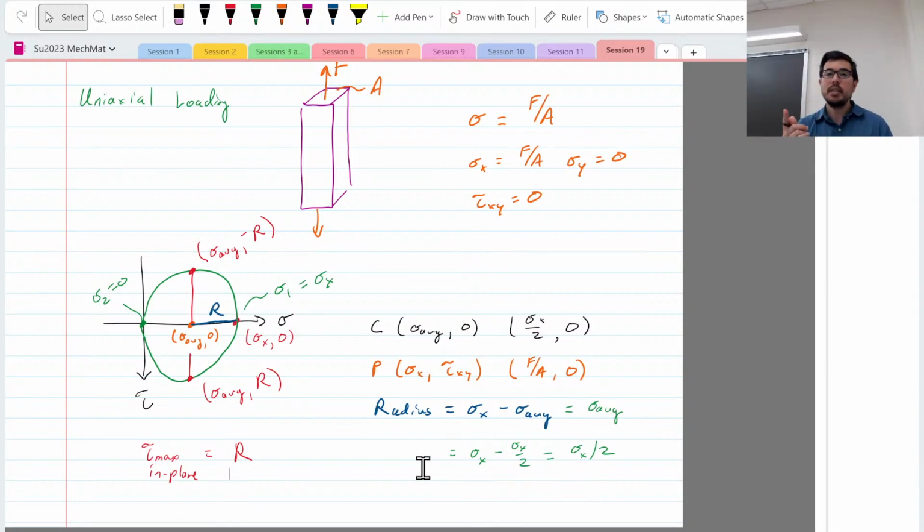Do you remember in the last exam, there was a question on question number 3, it said, here's a shear stress, shear strain plot. And you remember what we said? We said one approximation to make is that the shear yield stress, or the shear yield strain, is half of SY, half of the tensile yield strength.